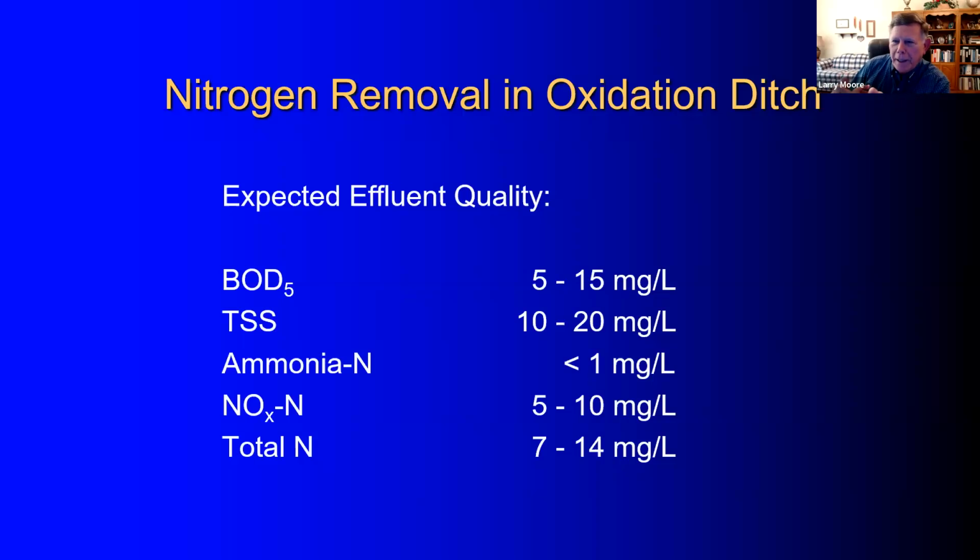All right. In a typical municipal wastewater treatment plant effluent, we're going to have about 1 milligram per liter of dissolved non-biodegradable nitrogen in the effluent. Okay. And typically, if we got about 10 suspended solids going out in the effluent, we're going to have about 1 milligram per liter of particulate organic nitrogen in the effluent.